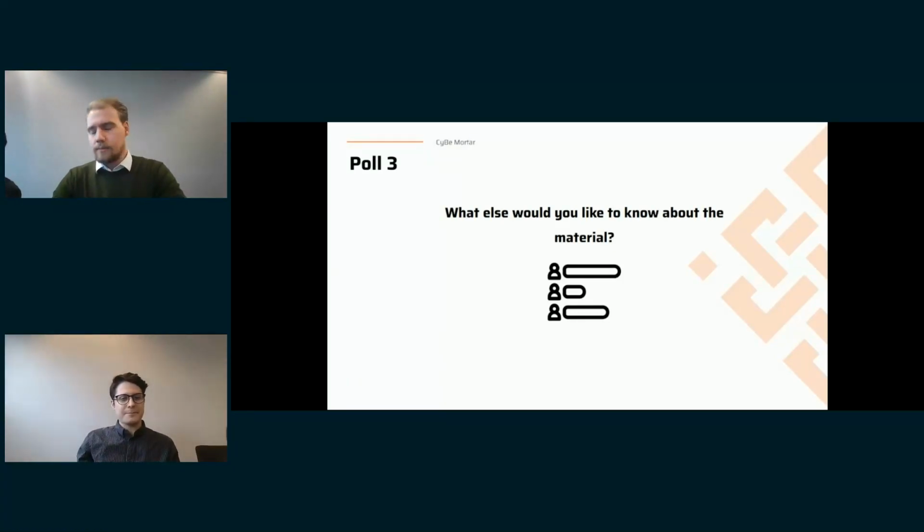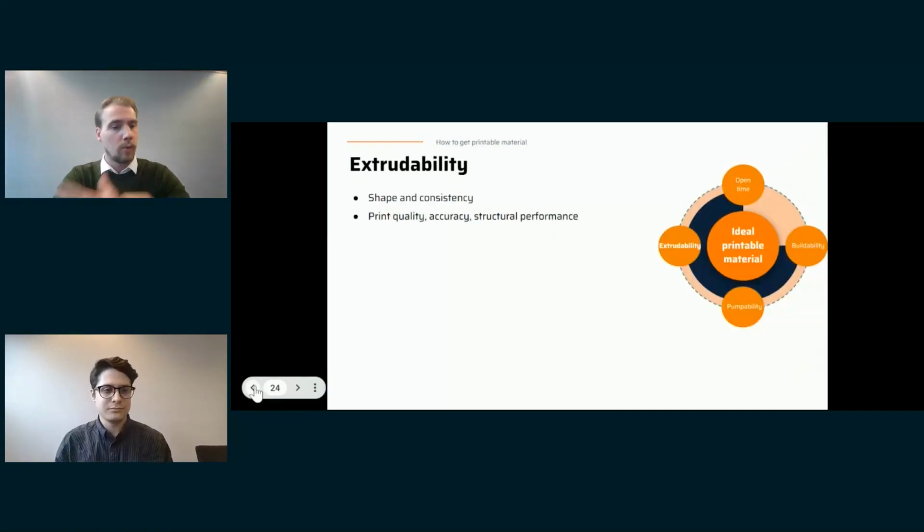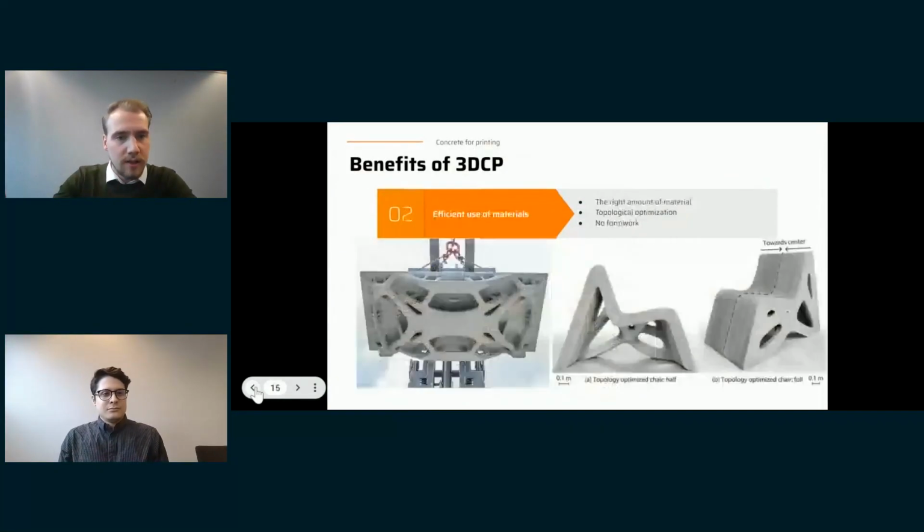Normally, we have talked about this before, but I will say it again: we use the wall elements as formwork, as lost formwork, in which we cast reinforced concrete. For this casting, we use, of course, a normal concrete, because there's no need to use 3D printing material. So for the structural parts, we adhere to worldwide building codes pretty much. Demonstrate in the video if you want.